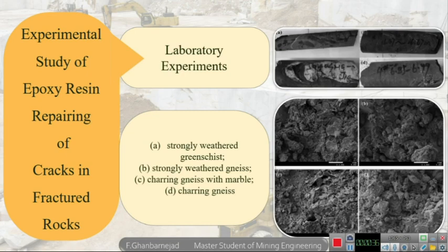The laboratory experiments to evaluate the grouting effect are based on the borehole coring of the epoxy repaired rocks. The rock core is a cylinder with a diameter of 56 mm. The rock core is prepared to a cylinder with a height of 100 mm and diameter of 50 mm for uniaxial compression and water penetration tests.